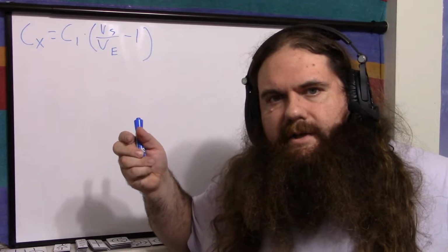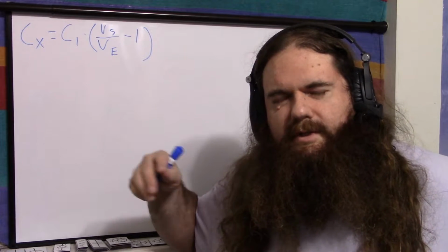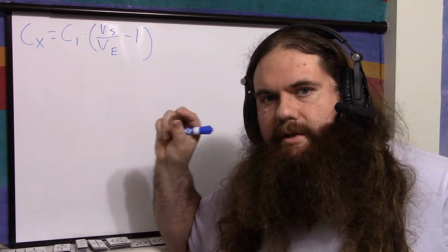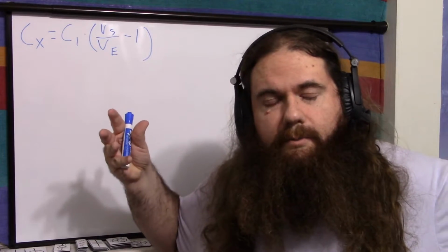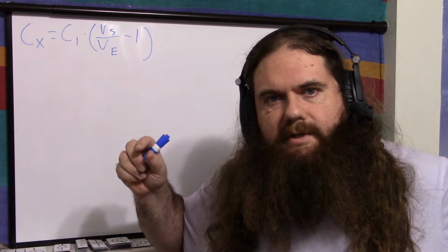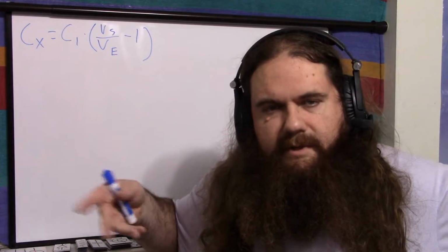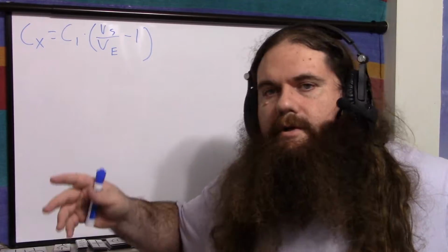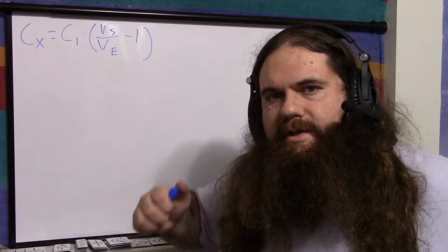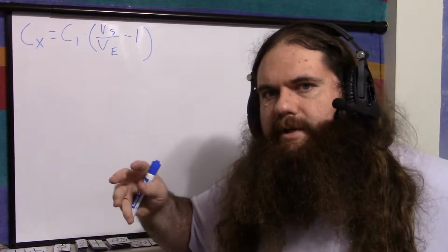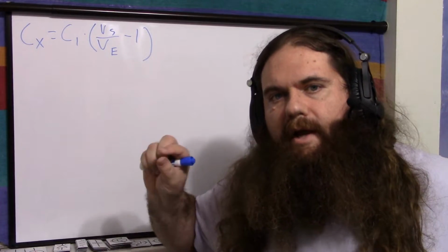Now, in testing this, of course, the voltage that I actually measure is not the voltage that it's supposed to be, because the known capacitor has a variance. All capacitors have a variance, all components have a variance. So when you get a capacitor that says it's 6.8 microfarads, that's plus or minus 5%, 10%, 15%, whatever. So you do these calculations and you're going to get an error because you didn't actually technically fully measure the known capacitor. You're going by what it should be, and that's your error.